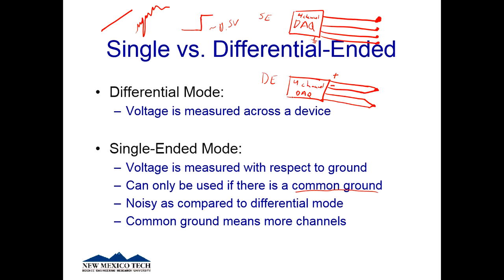But anytime you have long connections, anytime you need to run long wires to a sensor. Anytime you have little tiny step changes, versus these big step changes, if you have a noise signal on it, maybe it doesn't matter. So that's why you can get away with single-ended.